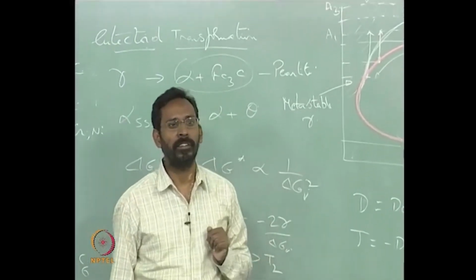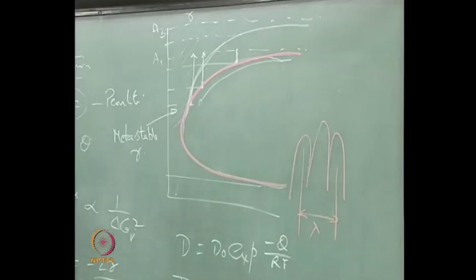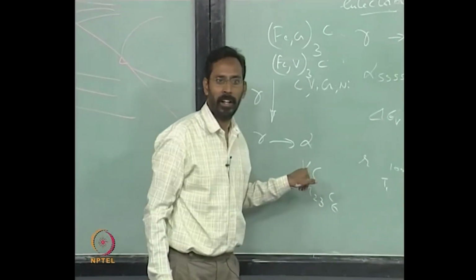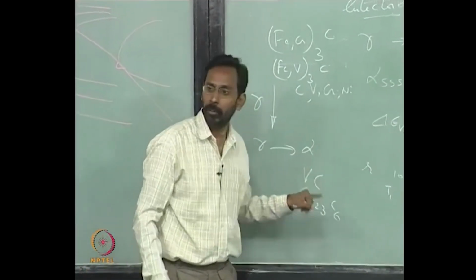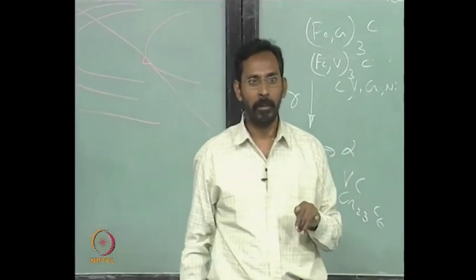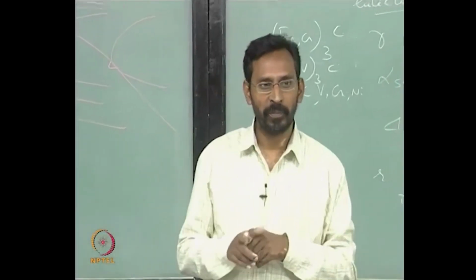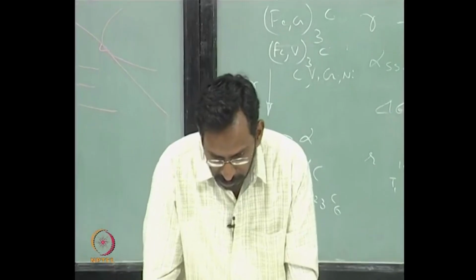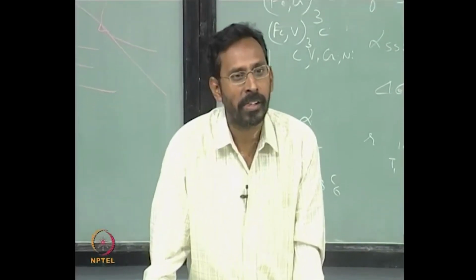How does it get affected? Tell me. What happens, let us say I have vanadium or chromium or any other carbide forming element and I am cooling this now. So the moment I am cooling it, because there is a greater affinity, it will shift to the right. Sure? Yes, why? Because the diffusivity comes down. Why? Concentration of carbon decreases. So what?